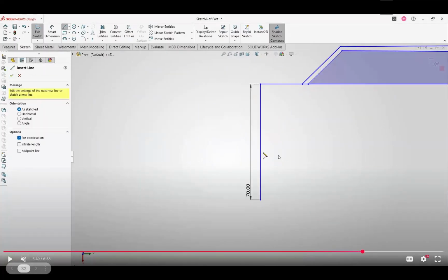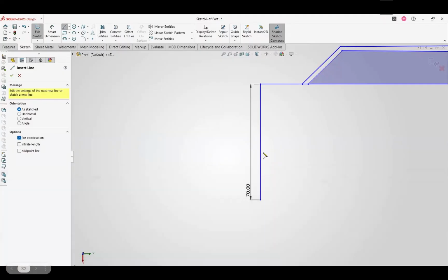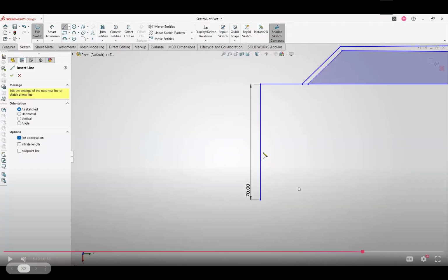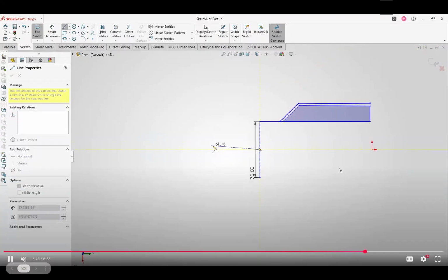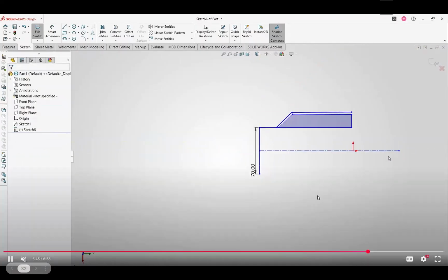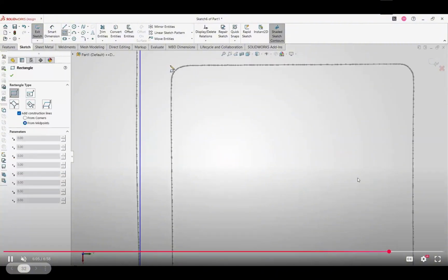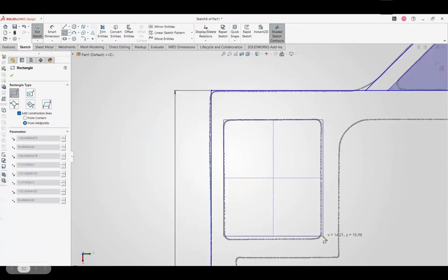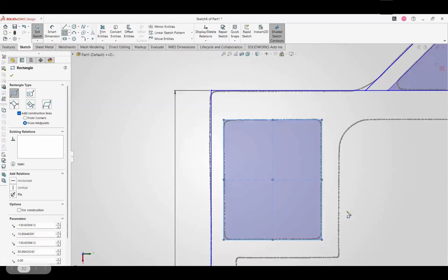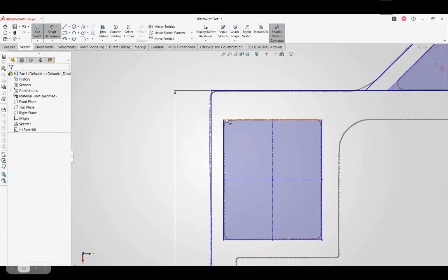Yeah, when you create center lines, it's actually easier to create center lines without visualization of the section, because in this case you can avoid unnecessary constraining to the section. And the same applies to all other objects, as I said, as rectangles. So you place the rectangle more or less according to the section, and you start dimensioning it.